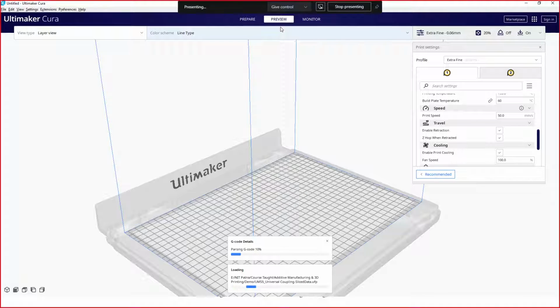So one issue may be that when you have clicked on your print button, you notice that your first layer got printed correctly, but maybe it is not adhering. One layer is not adhering with the second layer, or maybe the first layer could not adhere to your printer bed. Then the material will not be printed properly, and the part which is being printed may get distorted, or some other issue may arise.